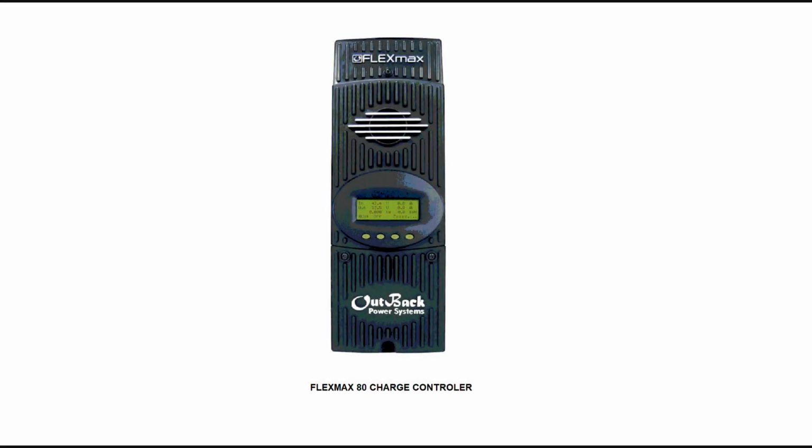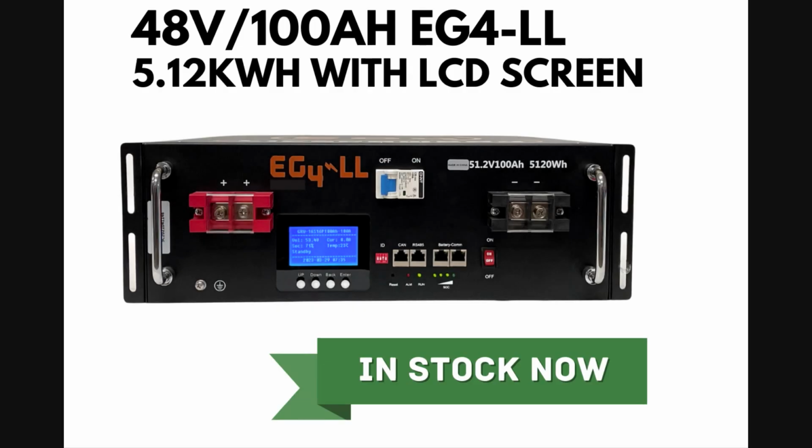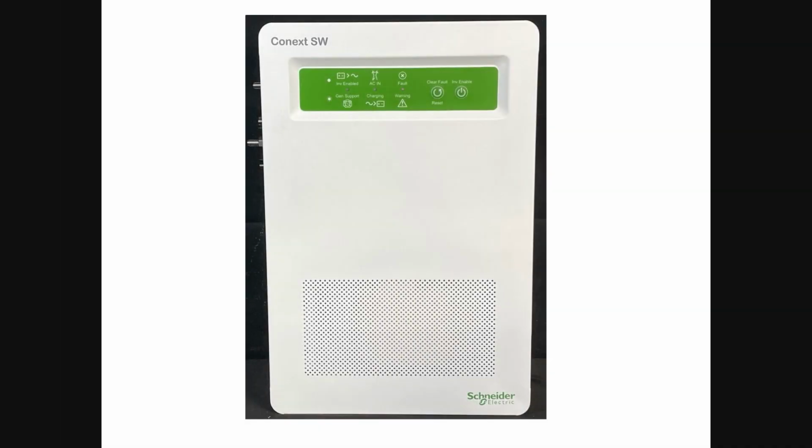The FLEXmax 80 charge controllers have a built-in RJ45 data port, but its output data was much more complicated than what I wanted to tackle with this project, as it was going to be my first project utilizing a Raspberry Pi, the Python programming language, the Flask web framework, and the HTML web page markup language. The EG4LL batteries use a fairly straightforward form of the Modbus communications protocol in a request and reply system to retrieve the data from the batteries. The Schneider Electric SW inverter uses Modbus similar to that of the EG4LL batteries, but it too was slightly different.